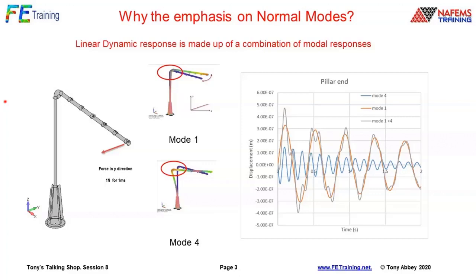If you've got something like a car roof, you're looking at very high frequency acoustic response, you've probably got thousands of modes, and to pick up the subtlety of those mode shapes, you normally need about 4 or 5 elements per wavelength to capture the mode shape. And if it's such a small wavelength, then the mesh just gets ridiculous.